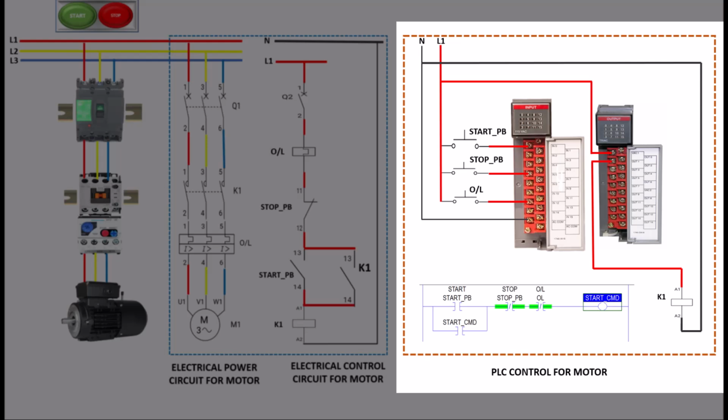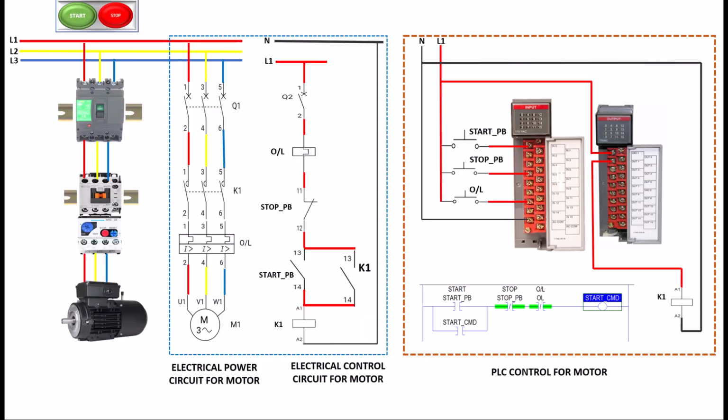It has the same setup to the motor through the programming as we did with the electrical control. It has the advantage that you have to use less wiring and get more productivity as per requirement. In case anything needs to change process-wise, you just need to change the program instead of wiring. This is the basic advantage of using a PLC.